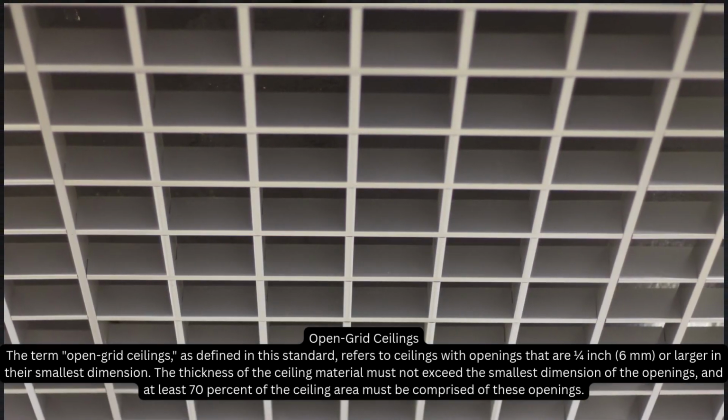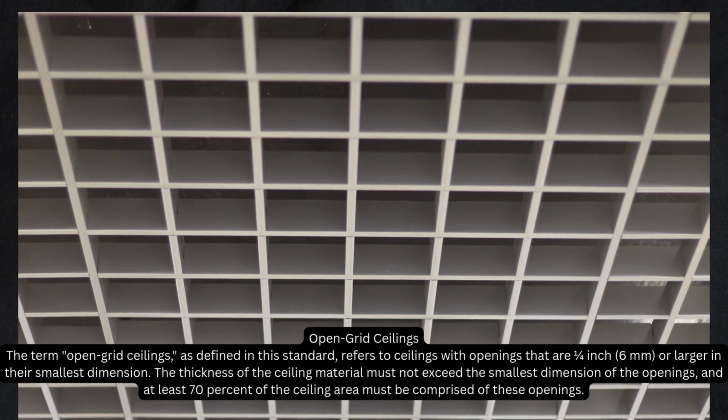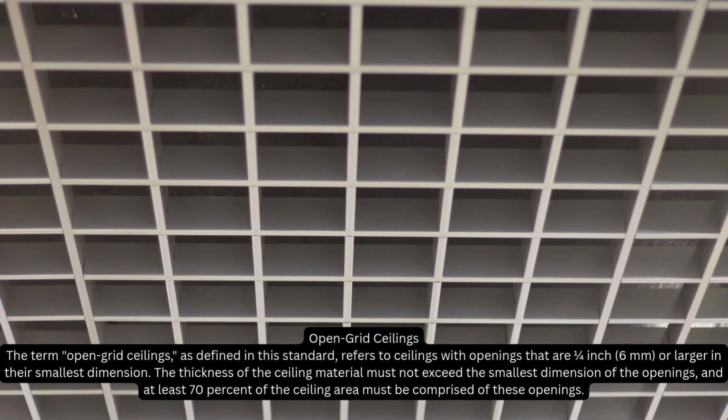Open grid ceilings. The term open grid ceilings, as defined in this standard, refers to ceilings with openings that are 1/4 inch, 6 millimeters, or larger in their smallest dimension. The thickness of the ceiling material must not exceed the smallest dimension of the openings, and at least 70% of the ceiling area must be comprised of these openings.